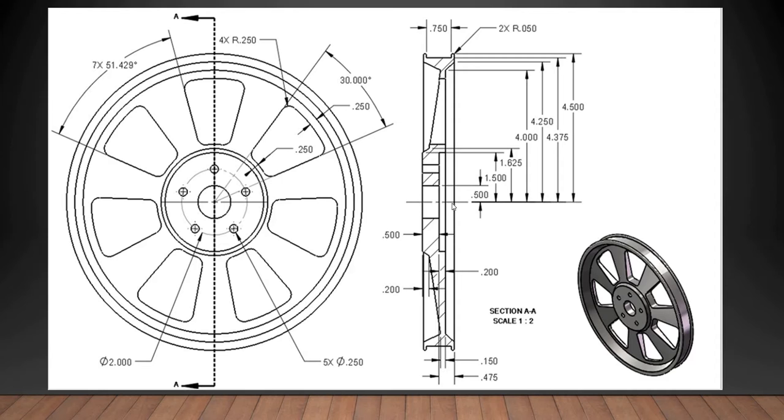So when we first start our sketch, you're going to start ½ an inch above your axes in Sketchup, and then we're going to draw this little section right here, and it's going to be drawn separately, and then we're going to copy it. We're going to make a component, and then we're going to copy that component 7 times around, and then we're just going to do a trim and knock everything all out at once.